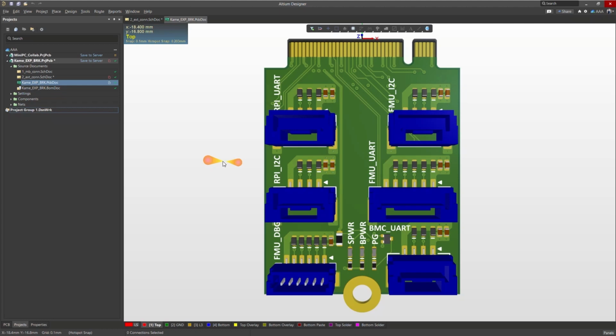The difference between a snippet and a design reuse block is that a design reuse block can be synced between the schematic and PCB, and also it is a managed item in your Altium 365 workspace, so it can go through a life cycle and approval process and so on. Whereas snippets were more like a perpetual copy and paste, or you had a clipboard with different circuitry and you could paste that into your design. So this is a little bit more robust. So let's get into it.